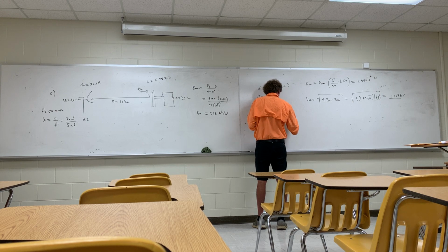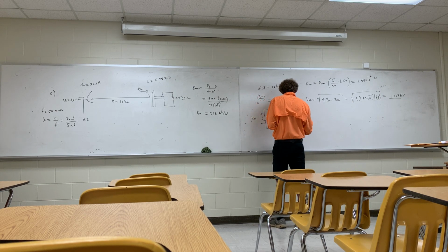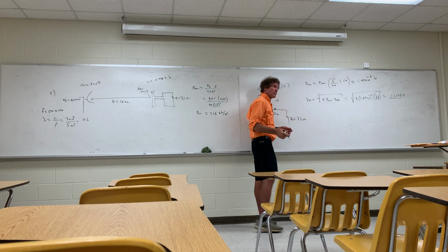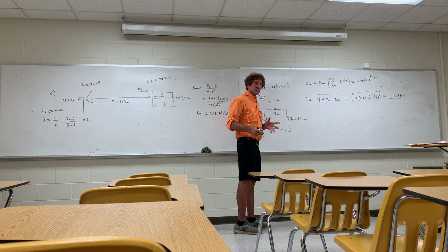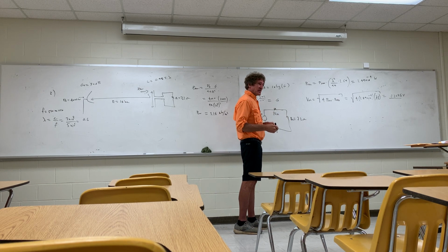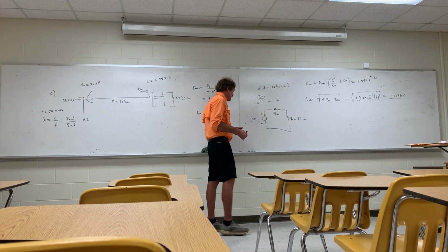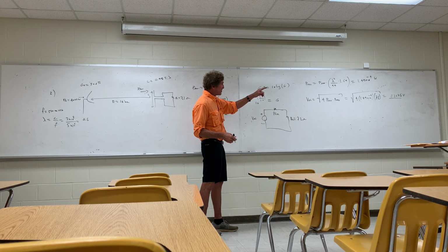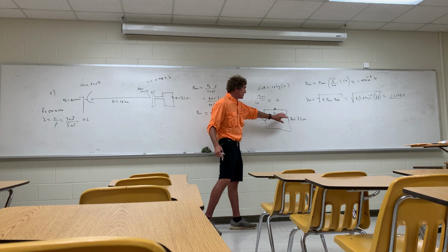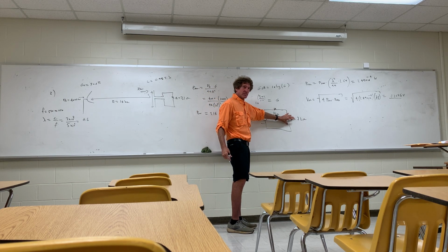And then I put this load down here, which happens to be the same, 72. On the final, I probably won't have these two equated, just warning you. So you won't be able to assume that that is going to be the internal resistance of the antenna, the radiation resistance. Now, taking one look at this, if you know you receive that much power, you can just deduce half the power is going to be dissipated in the load because they're identical values of resistance.